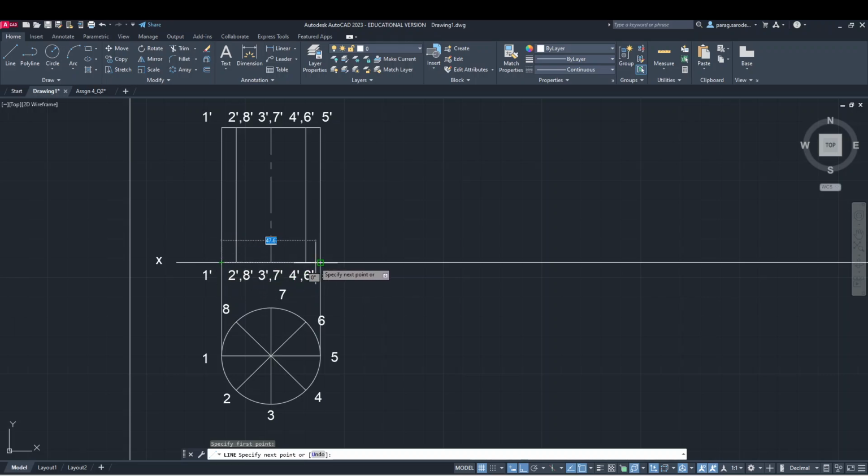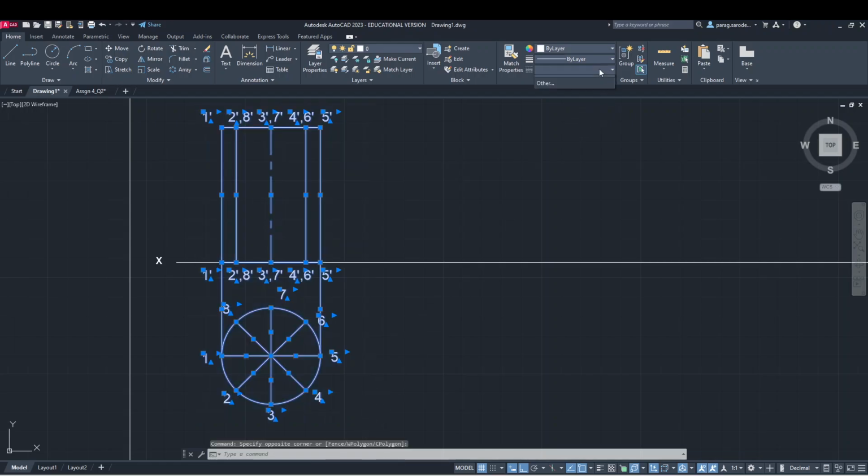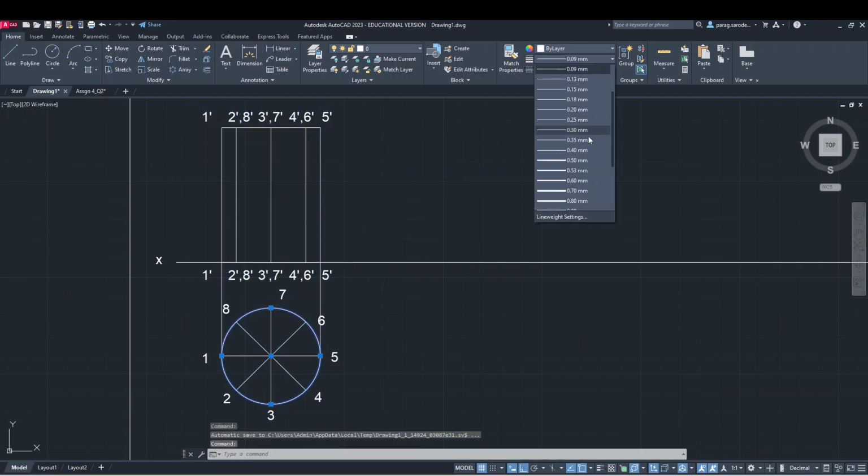increase the line weights. For that we will redraw this top base and the bottom base if required. So here we have redrawn the bottom base for making it thick. So let us select the line type, in this case as continuous, and the default thickness let us take as 0.9. Now let us select this circle and change its thickness to 0.3.